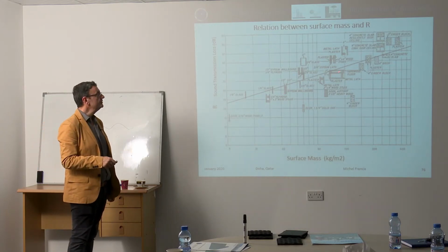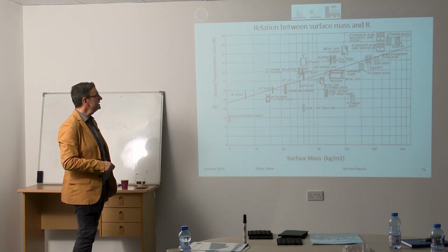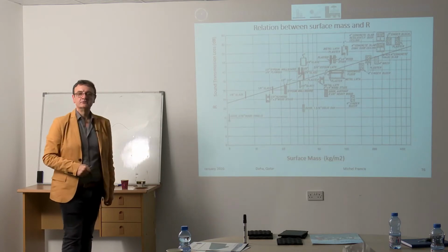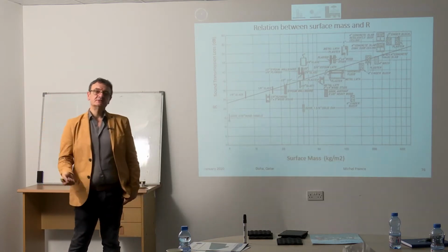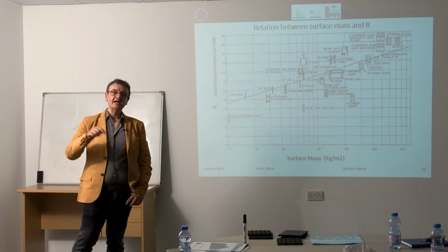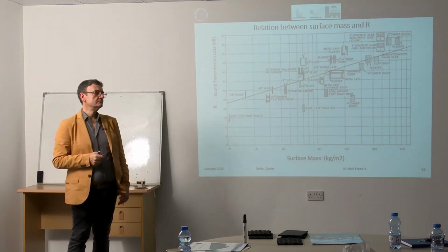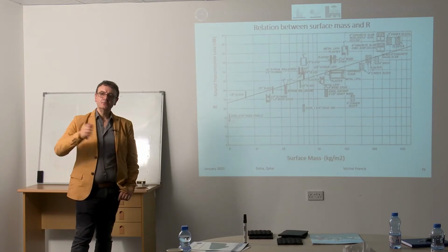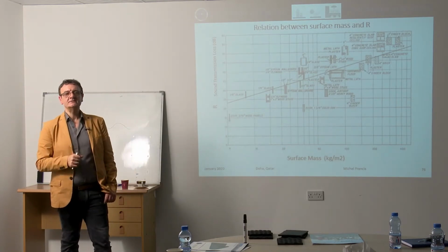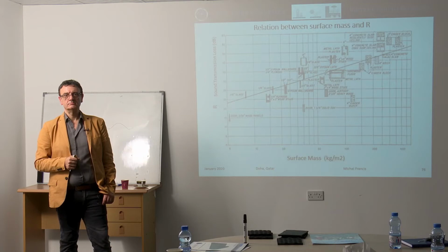By doing all these tests, they noticed they all fall in this range. That means the sound transmission loss is directly related to the mass. The higher the mass, the more loss you have. And that is the mass law.